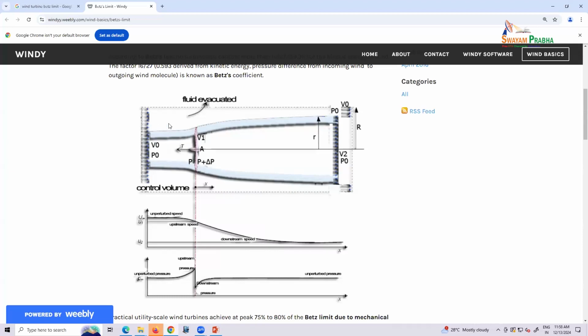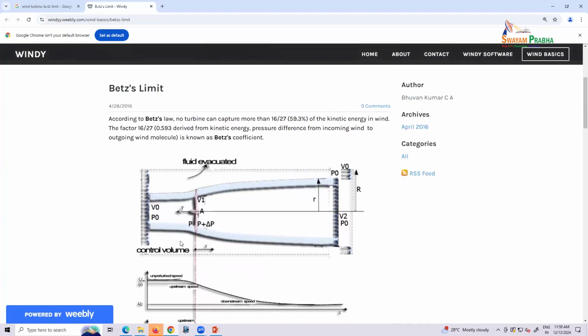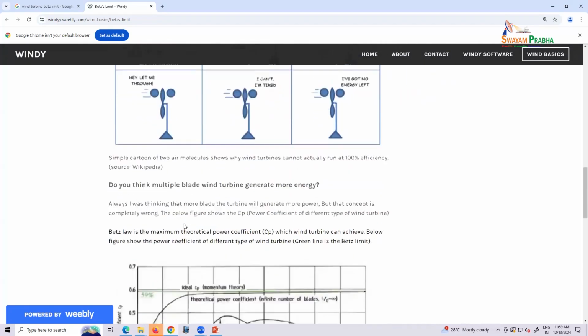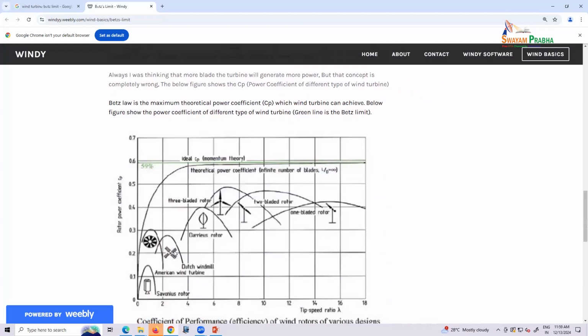And what if I put a wall or duct, right? Then for the flow line we don't have such a constraint. Then we don't have such a maximum speed, maximum power as a function of the speed. Okay, so this is the Betz limit. Okay, so keep in mind this figure shows efficiency.